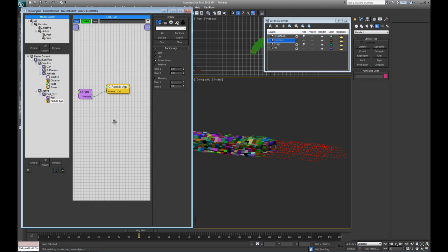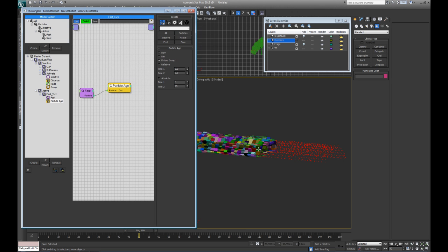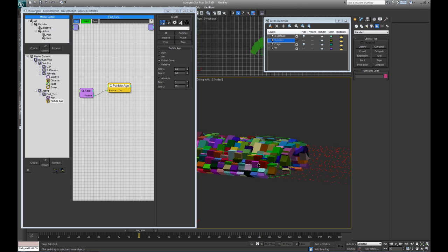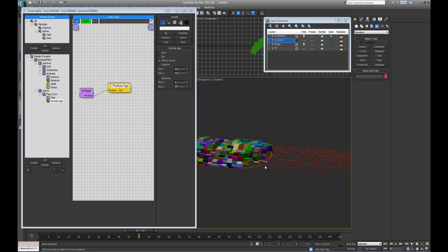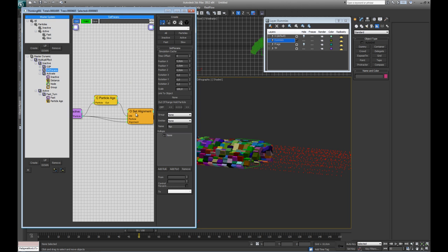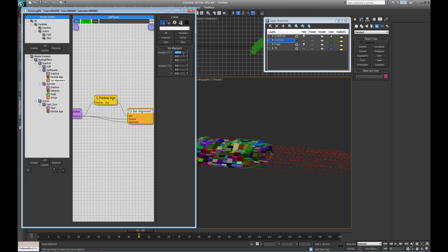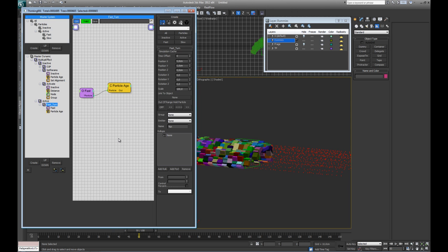So what we're actually gonna be doing is rotating the particle over several frames until it hits the original rotation or alignment. So if you remember, in the set params, we've used the set alignment, and we actually rotated 180 degrees, which I found is kind of the standard, half a circle. So it's giving this build-up effect. It also makes sure that when the particles are born, the new particles are actually facing the old ones, so it just makes the effect look quite nice.